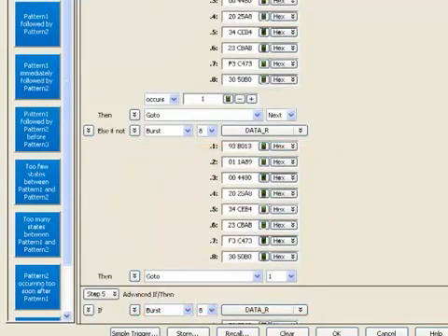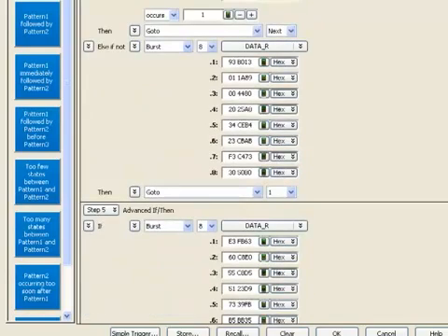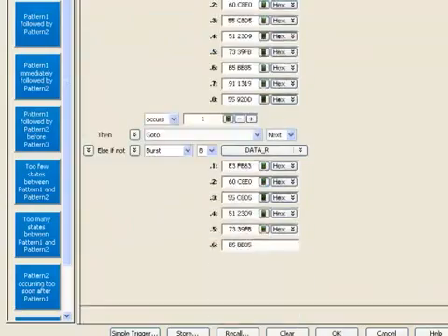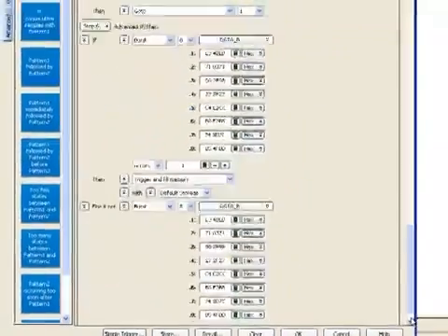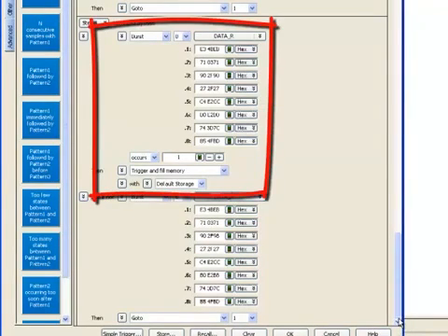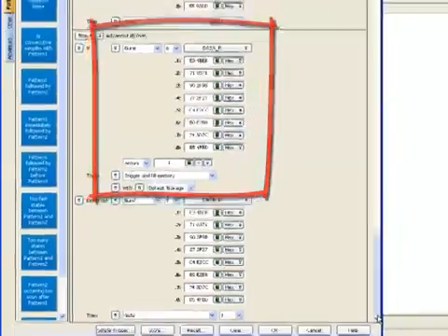The sequence continues looking for the second burst of 8, and if it isn't that, we go back and look for the next valid read. Again for a third, and finally for an exact pattern, the fourth exact pattern of 8 samples in a burst of interest, and here we'll trigger when we find the pattern.